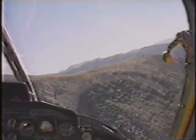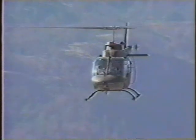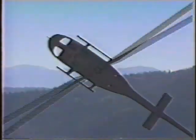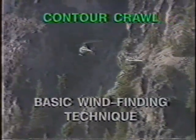Once you get close enough to the mountain to select a landing zone and begin to make recce passes, you'll be working in the boundary layer of winds, although at different points on the mountain, many other wind factors affect you. The contour crawl is the basic wind finding technique we use in the mountains. It tells us where the upflows and downflows are.